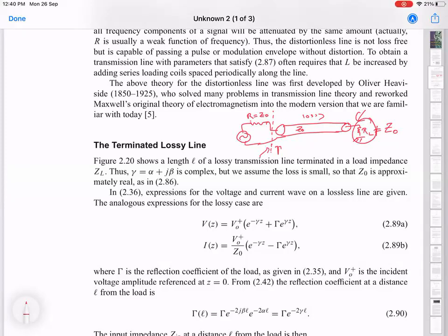So this again connects back to the point I made about the cryogenic experiments that you need attenuation. So then, does that mean that you cannot measure reflection coefficients of devices at cryogenic temperatures? No, because you use a different type of a device to divert the outgoing wave, the reflected wave, through a different cable.